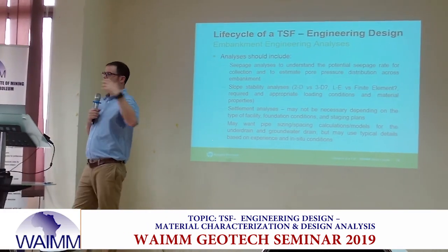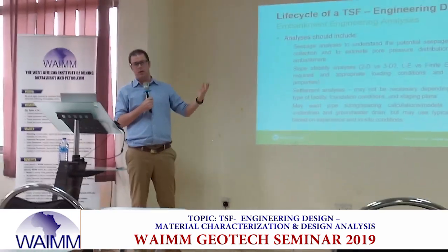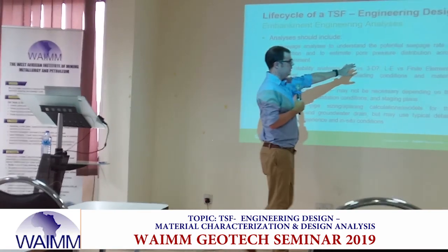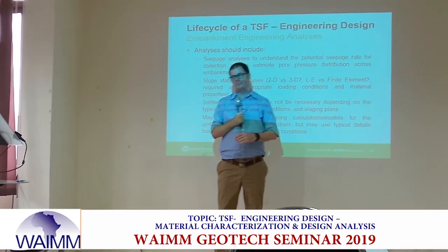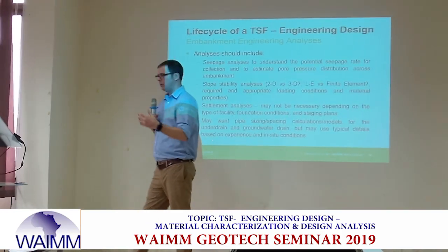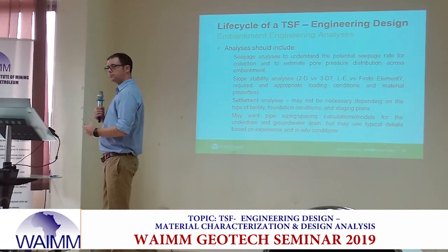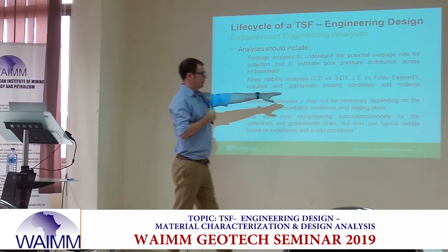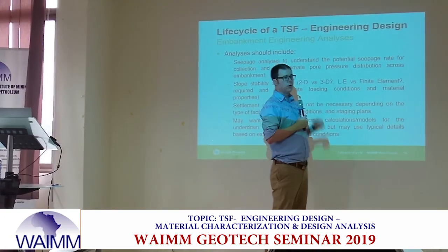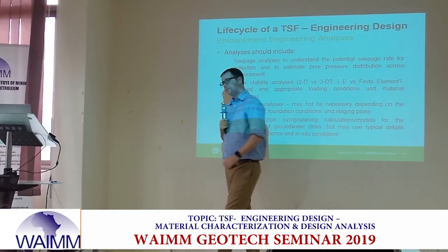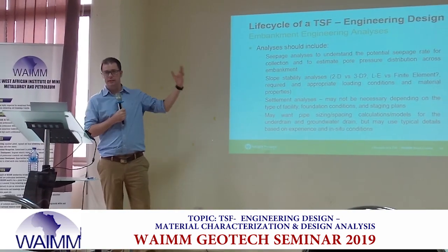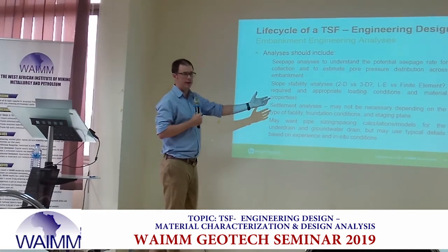It's only when those methods start becoming close that we might want to look at something more sophisticated like 3D or like numerical modeling. If we have a required factor of safety of 1.5, let's say, and our limit equilibrium is estimating a factor of safety of 1.4, okay, we may want to look at something more sophisticated if the conditions justify it.